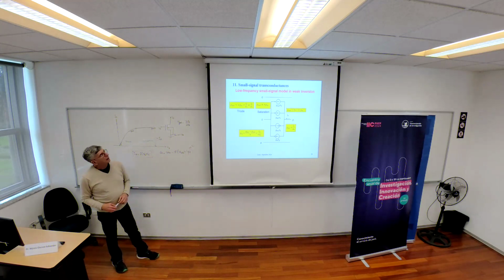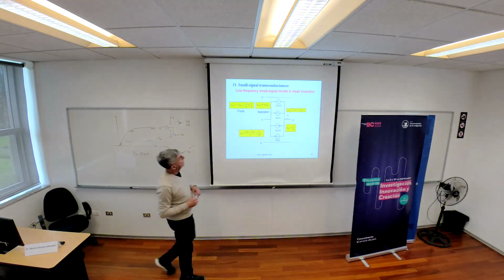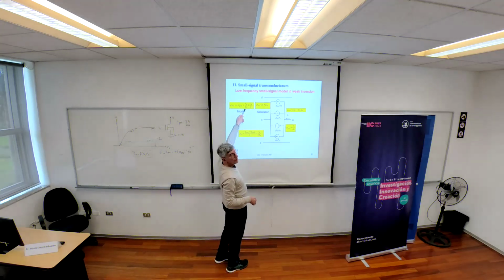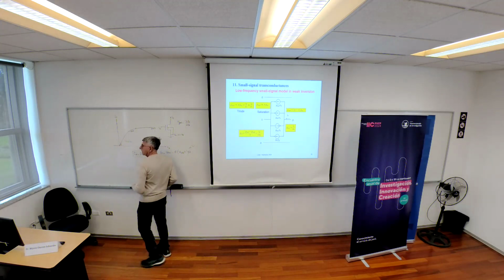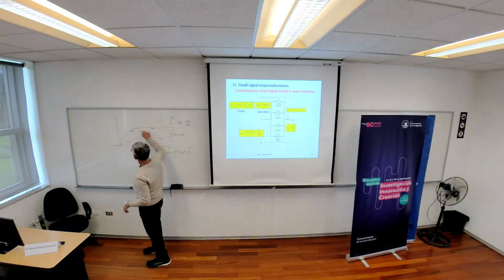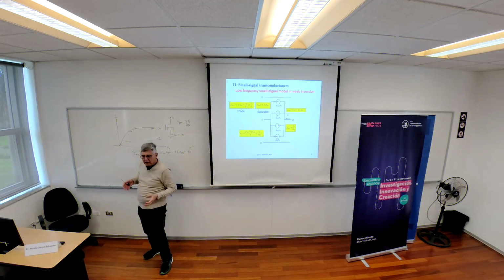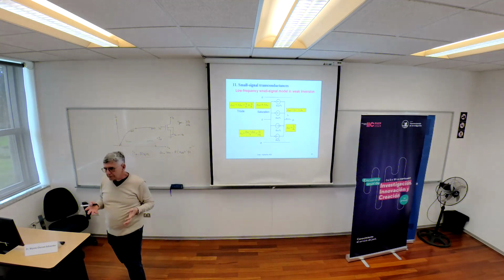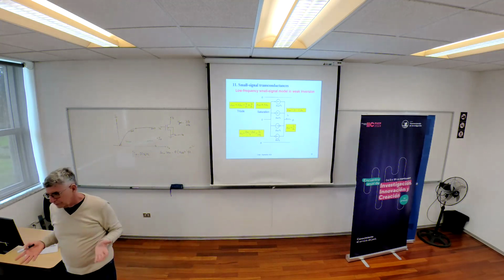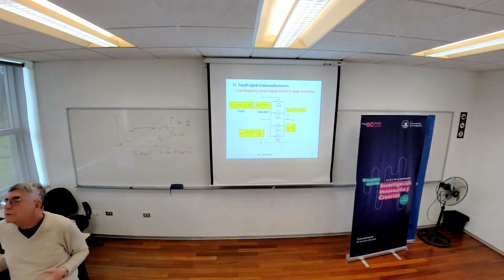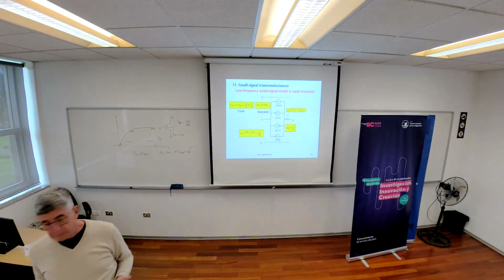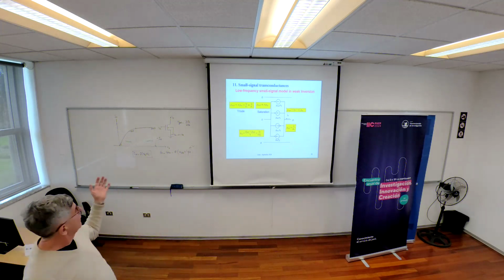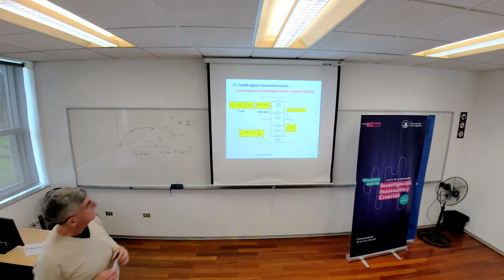Okay. So you have two terms. This one is the most important in the triode region. But somehow around this point here, maybe you need a combination of the two terms. Well, you should calculate or you should simulate something like that, to know what term is important, right?